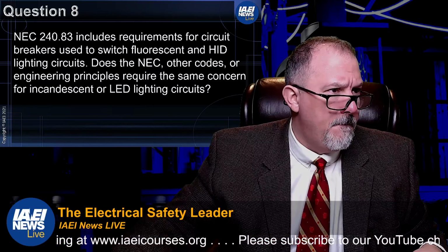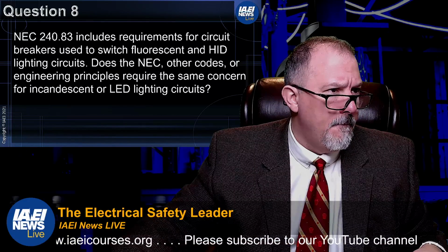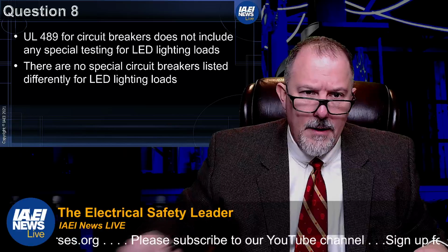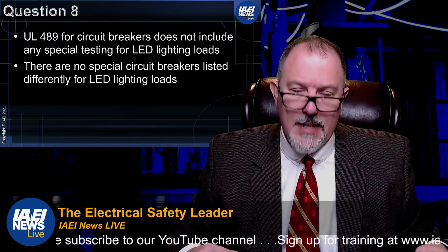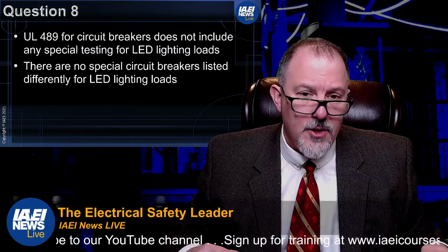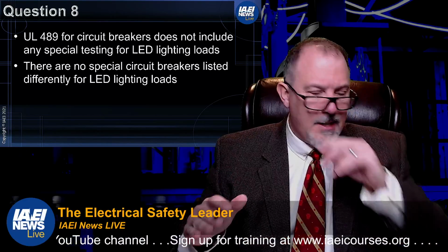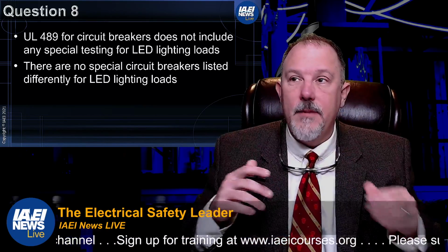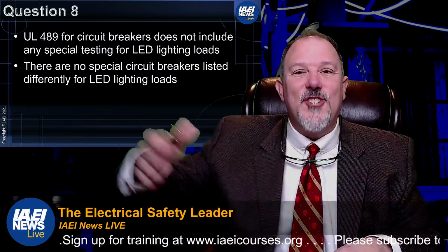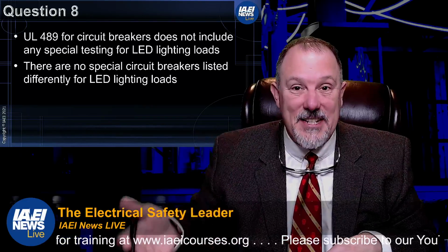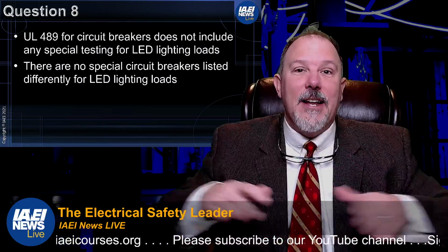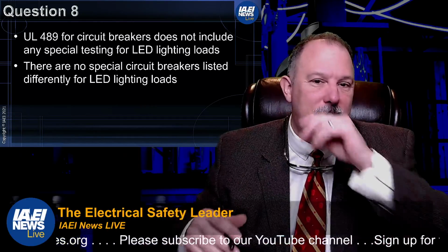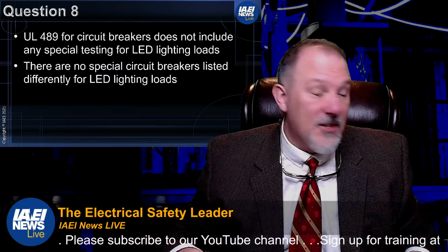UL 489 for circuit breakers does not include any special testing for LED lighting loads. So from an LED perspective, we have HID breakers for high intensity discharge. We've got SWD for switch duty. We don't have LED, for light emitting diode technologies, circuit breakers.